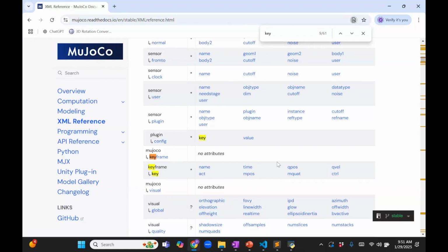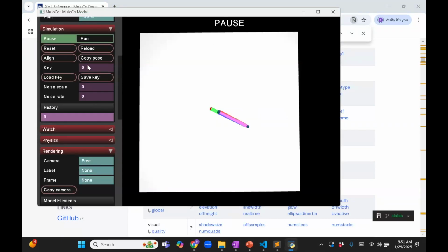Okay. So that's the first step. We've got the MuJoCo viewer to give us the XML. So this shows you how to take what we learned in the class with homogeneous transformation or the depiction of the body axis and transfer it to MuJoCo.